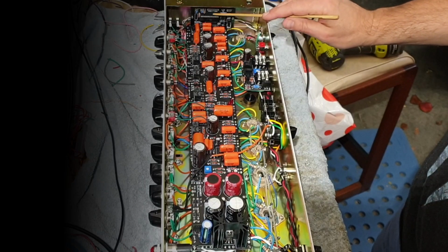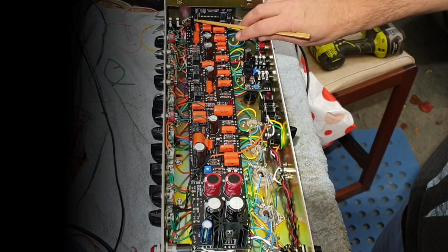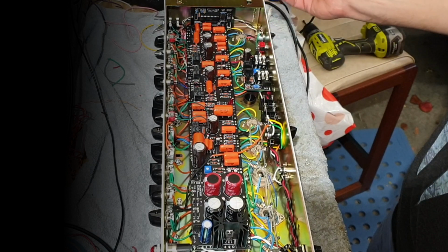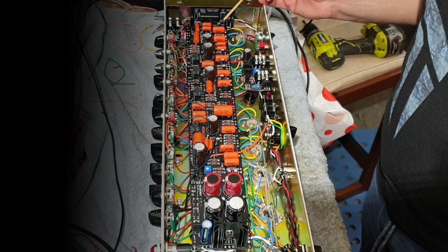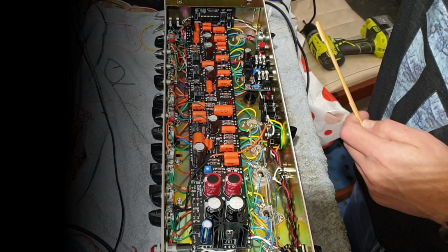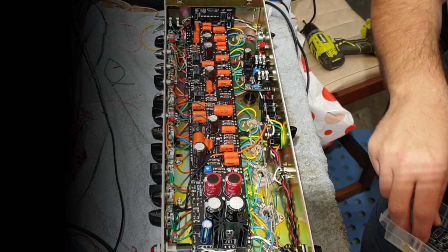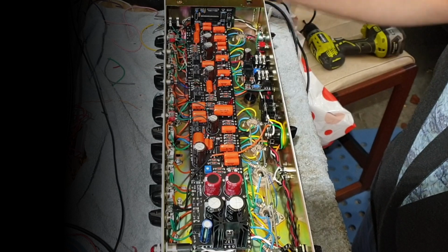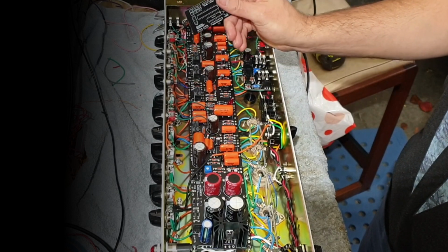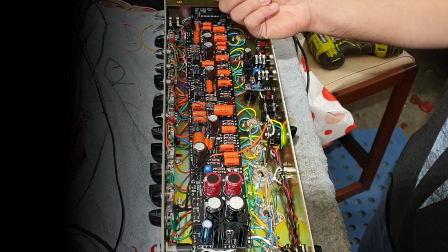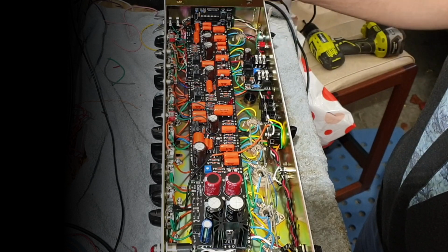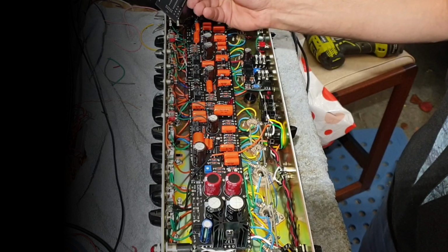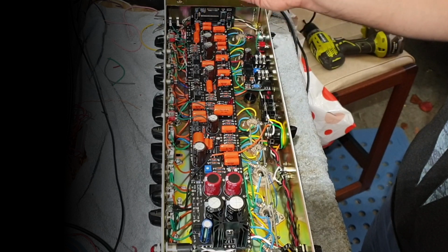Okay, so the MIDI board is now in. I've got two standoffs, one here, drilled into the side of the chassis. Just a tip, I've mentioned this before, but it's always worth remembering: before you populate your board, here's an unpopulated MIDI board. If you receive one of these from me and you're going to mount it into a chassis that is not pre-drilled for it, use this as a template before you populate it with components.